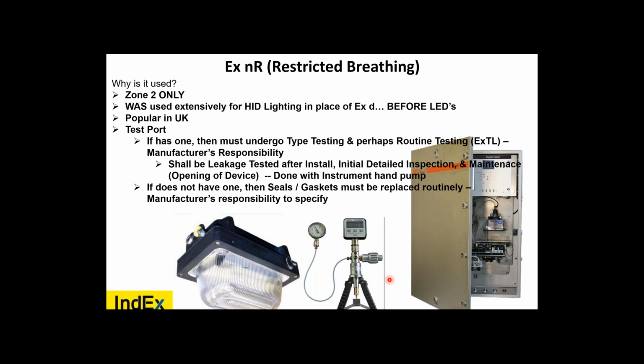I've been on some facilities that are 20 years old. How many times in 20 years have they changed that seal that was meant to be changed 20 times? Zero. Absolutely zero. So what are we looking at? Serious source of potential ignition. Manufacturer pushing all responsibility to the end user.